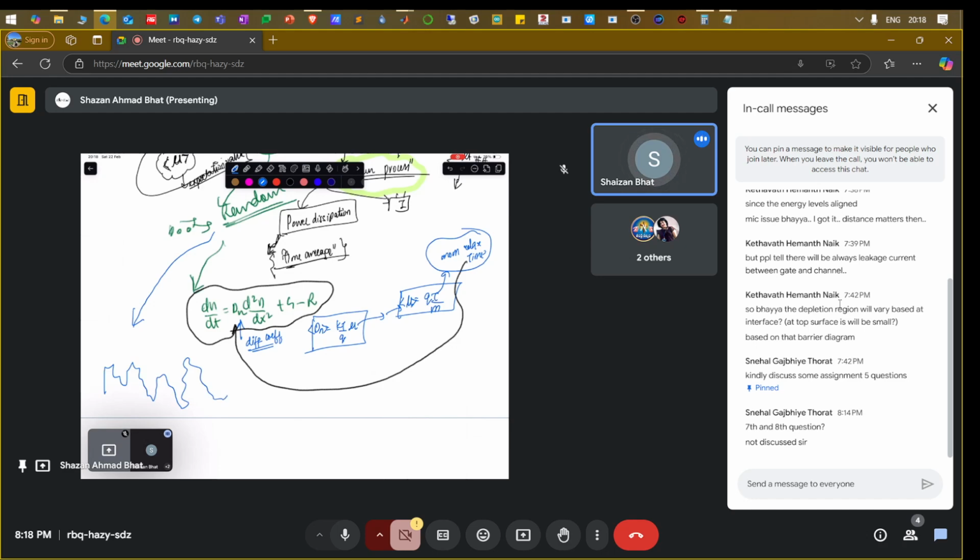Whenever you measure a current, if you measure a current waveform like this, then you take its average value, like a static DC value. But there is noise because there's a difference in the peak values compared to this constant value. So that is a source of noise, and it is because of carrier motion, because the current is flowing because of the carrier motion. Okay, I hope you got it.